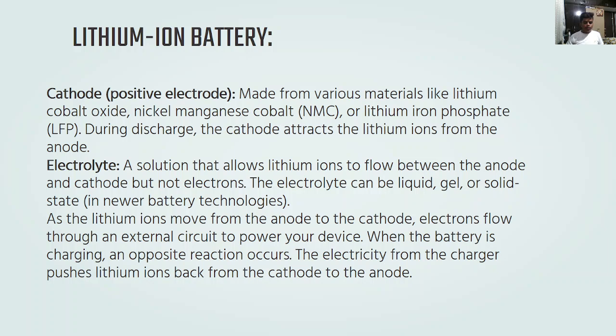As lithium ions move from anode to cathode, electrons flow through an external circuit to power your devices. When the battery is charging, an opposite reaction occurs. The electricity from the charger pushes lithium ions back from the cathode to the anode.